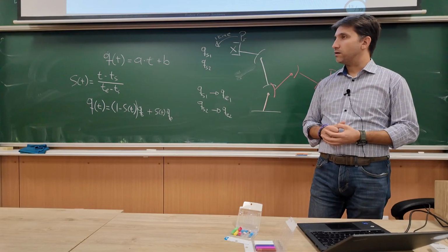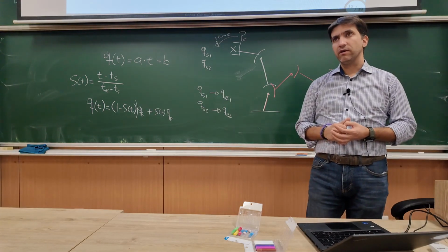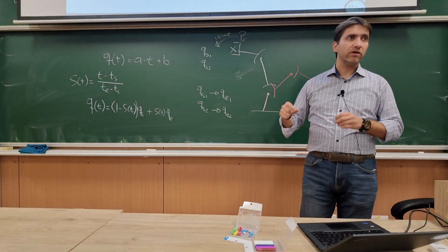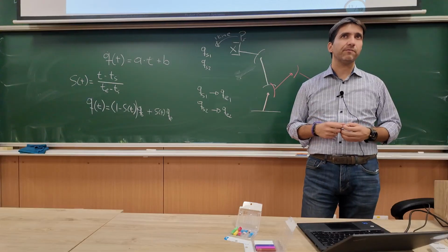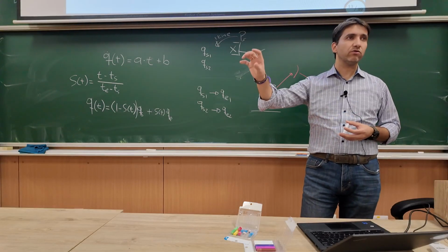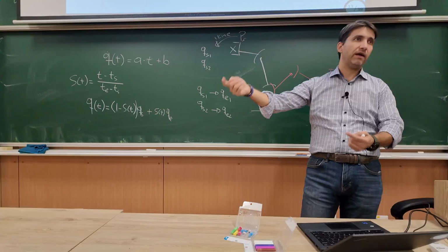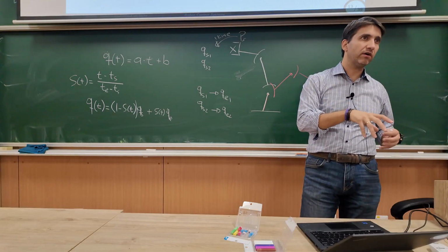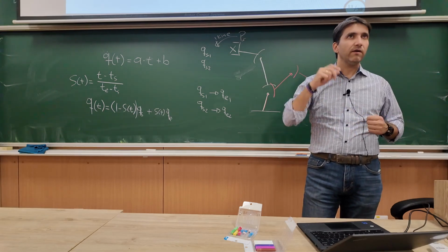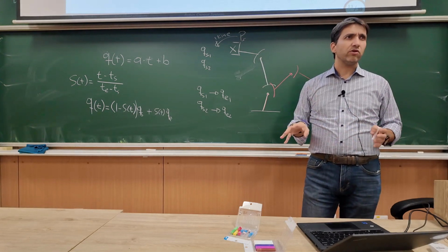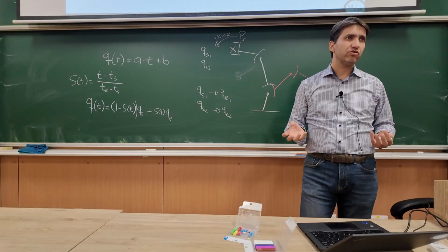a singularity. However, since we're really controlling the joints, singularities don't come into play at all, in the sense that singularities occur when we're trying to control the velocity of the end effector and we need to calculate the joint velocities to do that. As long as we're just controlling the joints, we don't have issues with singularity.